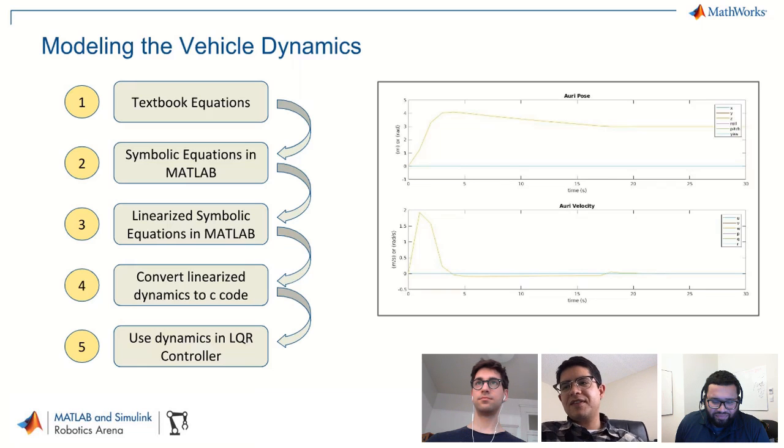What you see on the slide here is one of the very first basic LQR tests that we did. It's just a very basic depth test. In the top plot, you see the robot's pose, so the XYZ positions and then the orientation. The bottom plot is the velocities. It was very simple, but I remember that was very significant. It's the first time that everything came together. So this was definitely step one, then the simulator was probably the next phase, and implementing the actual robot was the last part.